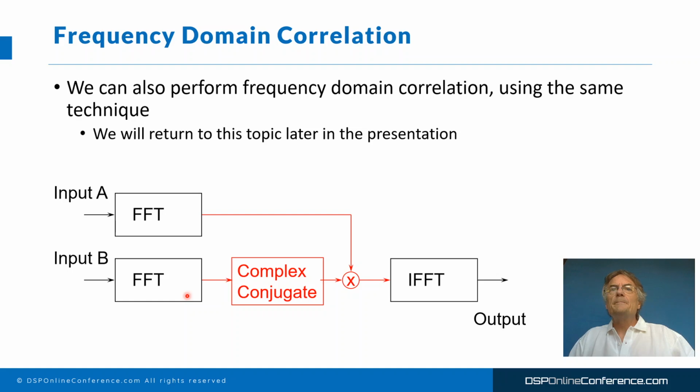Okay, as a side note, a final little side note, we can also perform frequency domain correlation using exactly the same technique. We just need to complex conjugate our input for our reference sample set. We'll come on to look at correlation in a little bit later in the presentation.